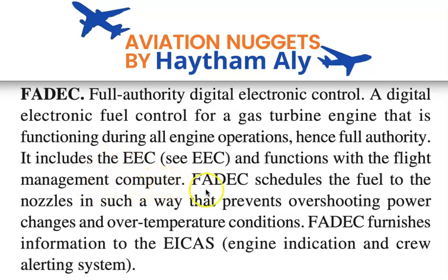The main function of the FADEC is to control fuel flow. So the FADEC schedules the fuel to the nozzle in such a way that prevents overshooting power change and over temperature conditions. This is what I just told you, that the FADEC protects against overspeed and over temperature.